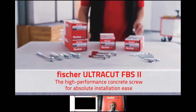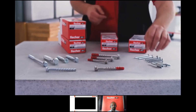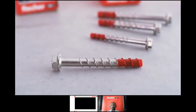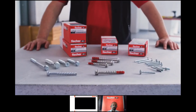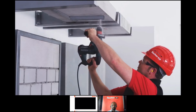Fischer Ultracut FBS2, the high-performance concrete screw for absolute installation needs. Zinc-plated steel with a diameter of 8 to 14, and in A4, and for the sanitary, heating and electrical industry, zinc-plated steel with a diameter of 6 mm. With unique screw geometry for simple and effortless installation.